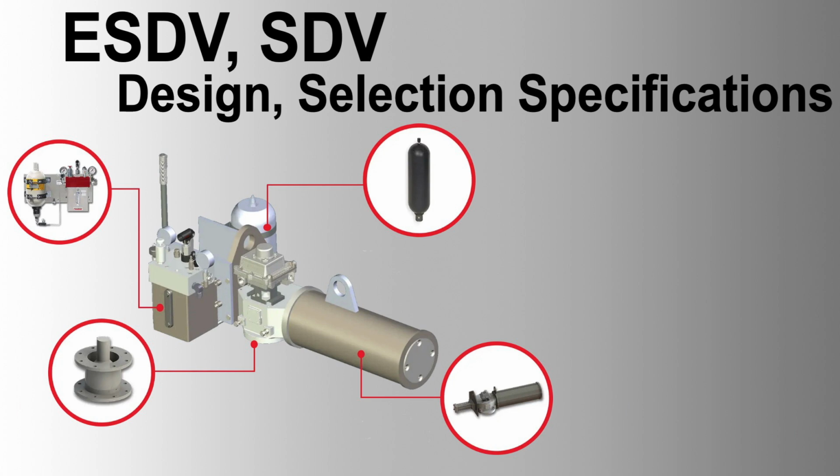Selection: material: compatible with the process fluid. Design: explosion-proof and suitable for the facility's hazardous area classification. 3. Actuators: type: pneumatic, hydraulic, or electric, depending on the control system and power availability. Design: fast-acting, reliable, and suitable for the operational pressure and environmental conditions.